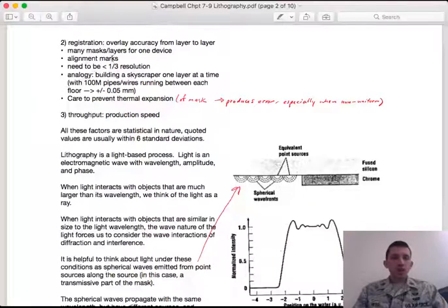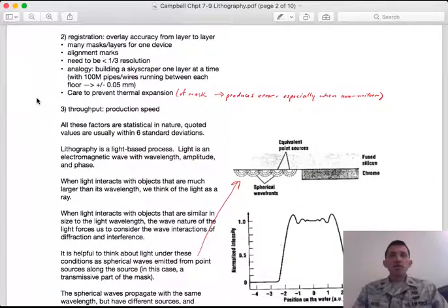And so not only do you need to be worried about alignment of the various marks on the various masks, but you need to be cognizant of the temperature of each of those, right? So each of these masks is going to be made of fused silica with deposited chrome, and fused silica has a coefficient of thermal expansion, right?